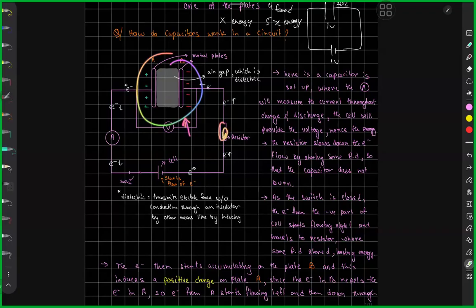Forget about the resistor over here. The resistor is needed in the setup for good reason, and I explained why. But for now, just know that the sharing of the voltage is negligible, and the PD that you will get using a voltmeter will be around 12 volt as well. So whatever voltage I'm supplying, the capacitor carries the same potential difference as the supply.